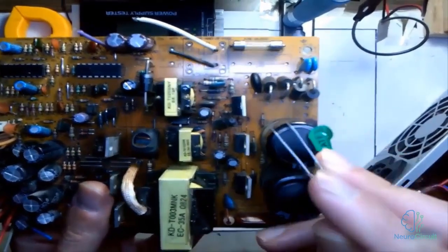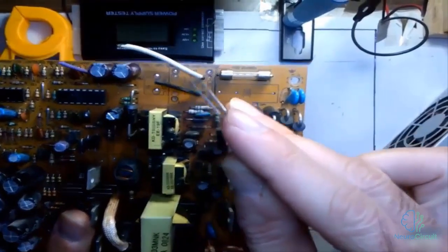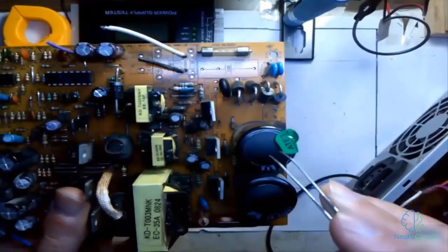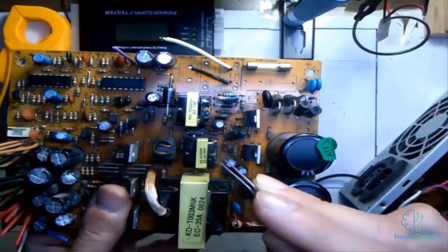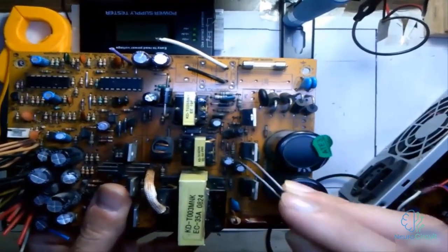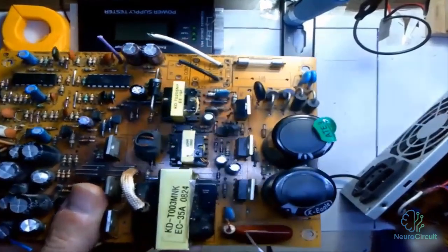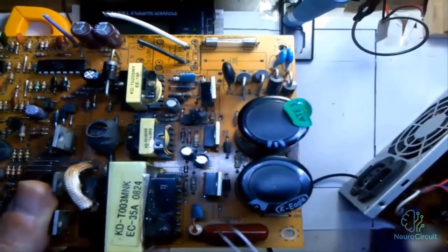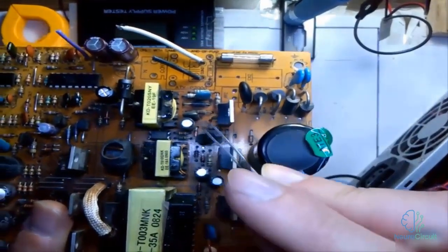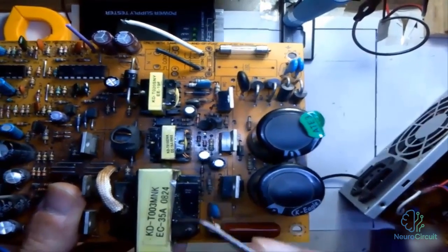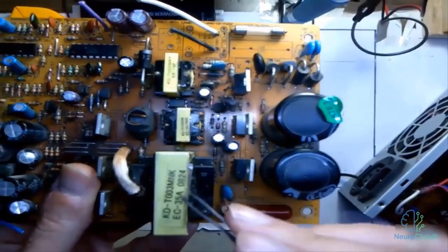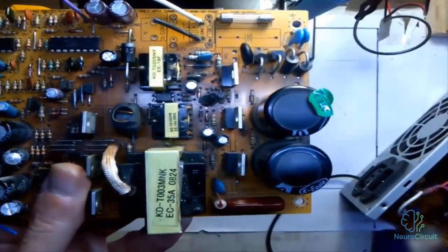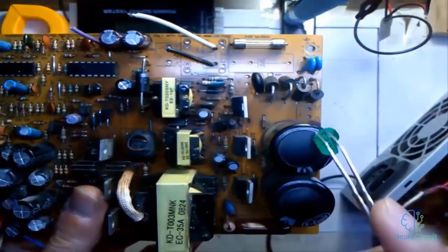So, the initial circuit works like this. The electricity enters here, passes through the bridge rectifier, goes through the capacitors, and is stored in the capacitors. Then it enters the start circuit. Here, through the transistors and other circuits present, such as the capacitors and the resistors that are placed here, the current is once again converted into a sinusoidal wave or sinusoidal pulse so that the transformer can use this wave. Now why is it converted back to AC here?